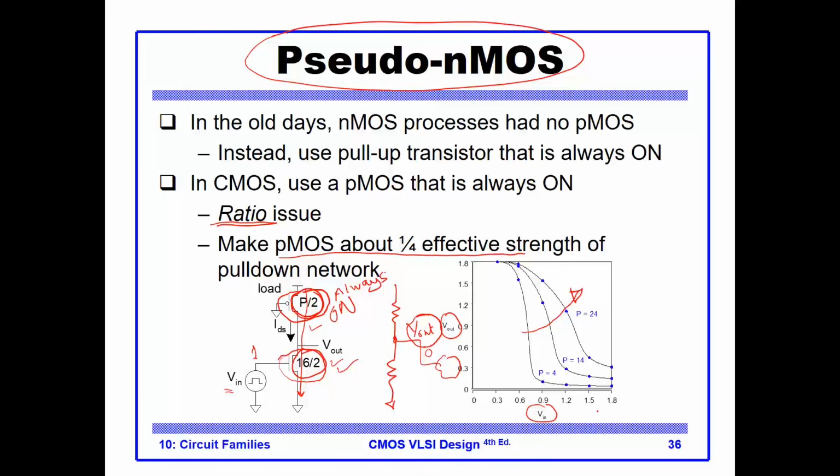So much so that you could end up with the V output at what we call V output low, that will not be interpreted as 0 with the receiving logic. So you really would want to have as steep a curve as possible.